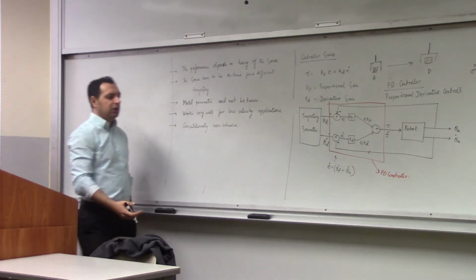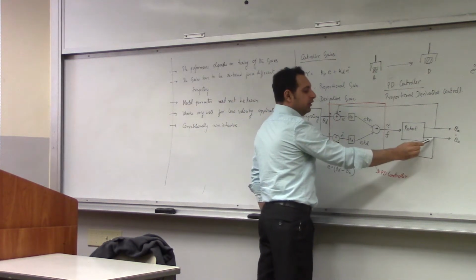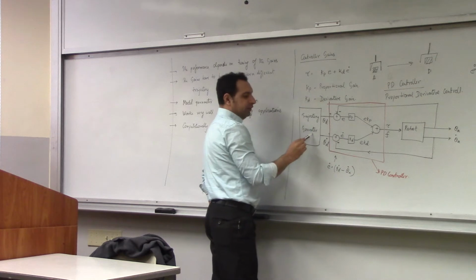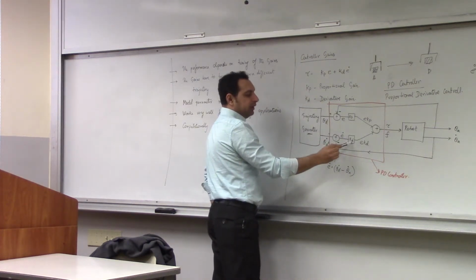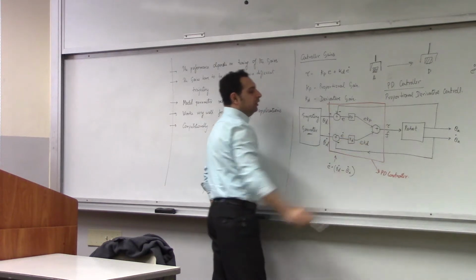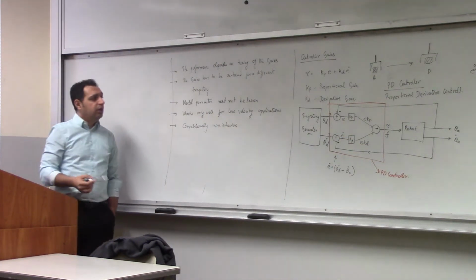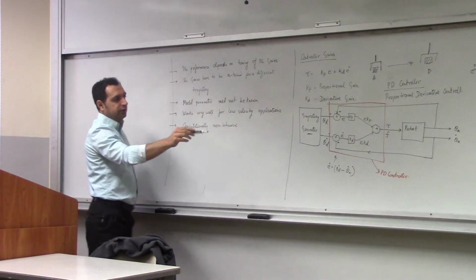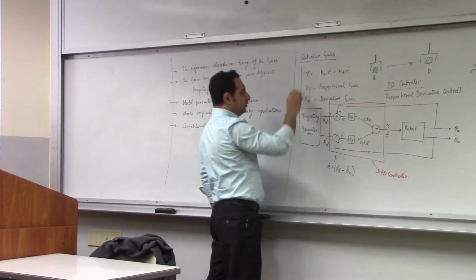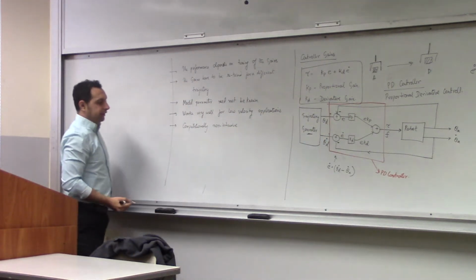It's very fast. This is your sensor output, which tells you the instantaneous position. Here you have a pre-defined trajectory. You subtract it, multiply by the gain, and add these two, that's all. So this is a very fast computational architecture. However, the disadvantage is that you cannot apply this for any trajectory. It works for a specified trajectory. Once you change the trajectory, you change the gains.